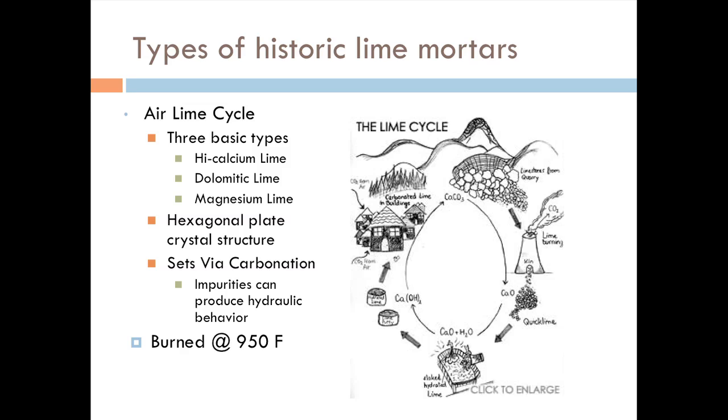Today, you would usually see it not in a putty, but in a powdered form, because just enough water was added to turn it into a powder so we could transport it. We're not spending all this time transporting buckets or 55-gallon drums of calcium hydroxide for building purposes in this very heavy form, or in a very caustic and dangerous form as quicklime, calcium oxide.